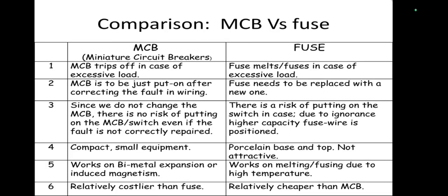Now we are going to compare the MCB and fuse. MCB trips off in case of excessive load, while fuse melts in case of excessive load. MCB is to be just put on after correcting the fault in wiring. Fuse needs to be replaced with a new one.